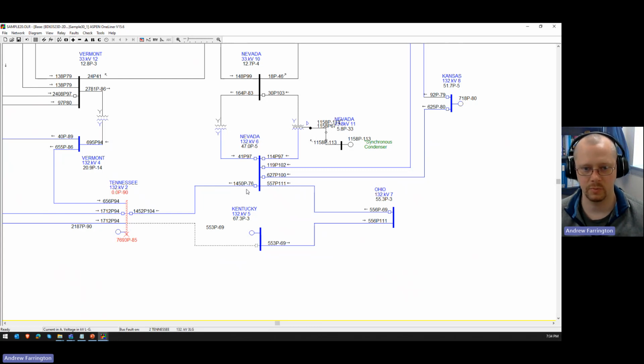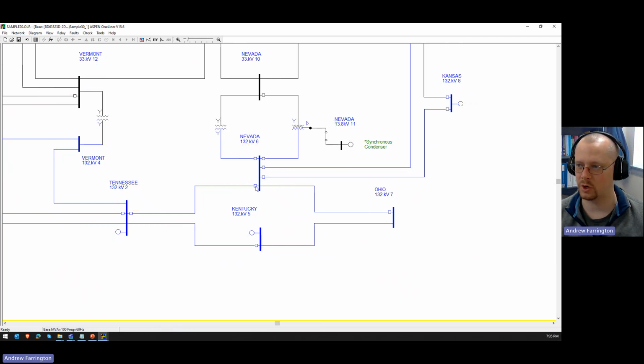So I would assume, well, that's with everything in service. Not necessarily. It depends on your network. And that was the point I was trying to make. It really depends. You got to play around with the model. You got to try things and see what happens, because sometimes when you intuit things, I know a client that has a standard that says to check, when you're setting the phase instantaneous overcurrent element, the fault with all lines in service.